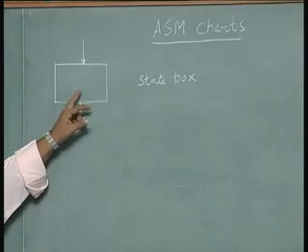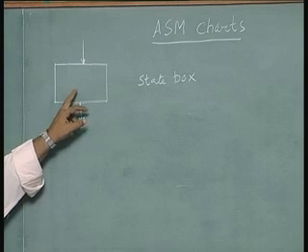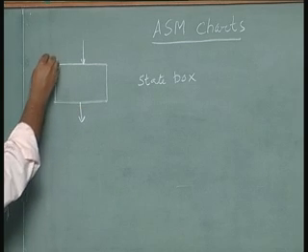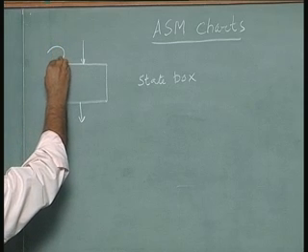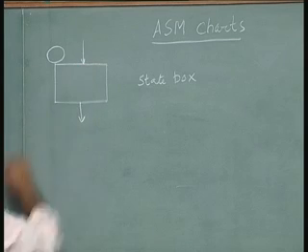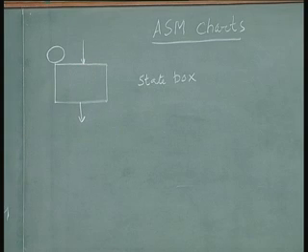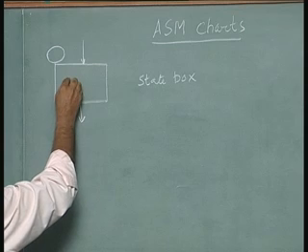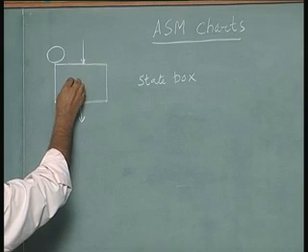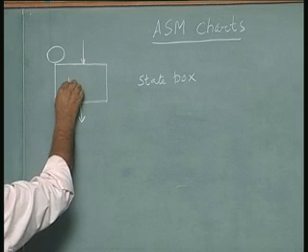So that is the same concept here, the state graph, the state box. The state box usually has a name associated with it. The name is given here on the left hand top corner outside the box, and inside the box you write the signals that will be generated as output in this state. So we will list, in this case, let us say load, as an example.